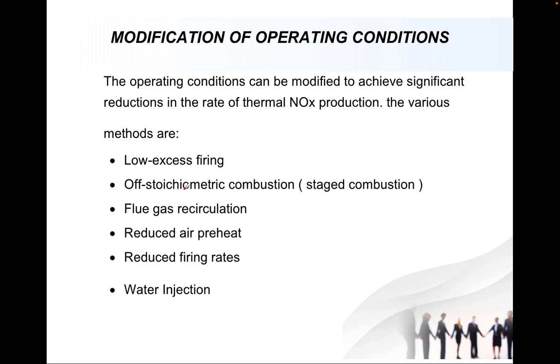If it badly affects the efficiency of the combustion, then it is also going to affect the fuel consumption, the specific fuel consumption, and it will indirectly affect the overall efficiency. So whenever we apply any particular method, we have to keep in mind that it does not negatively affect the other factors of the combustion process. So these are all related to the operating condition, and indirectly related to the combustion process also. Sometimes we inject water into the combustion chamber to reduce the average combustion temperature also. So these are some types of the methods.